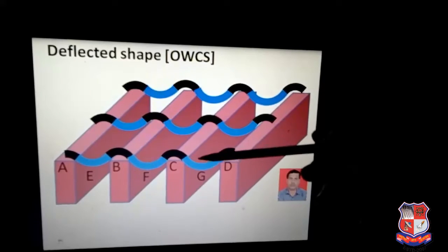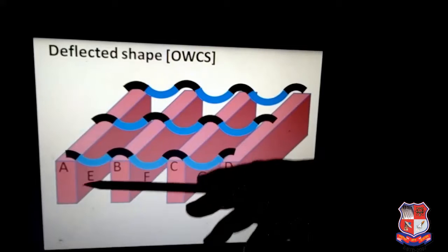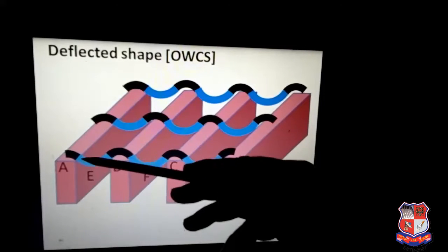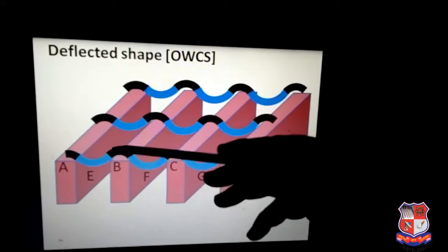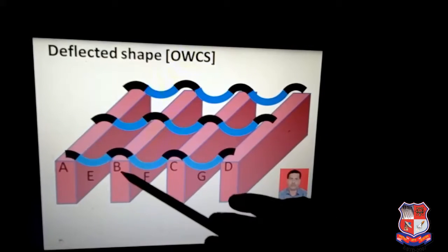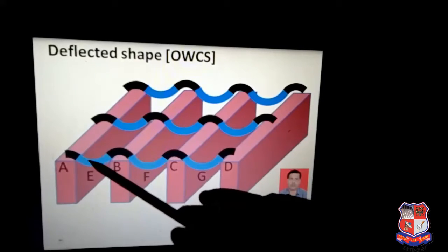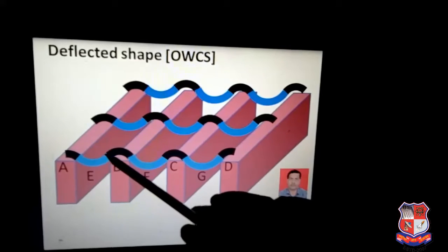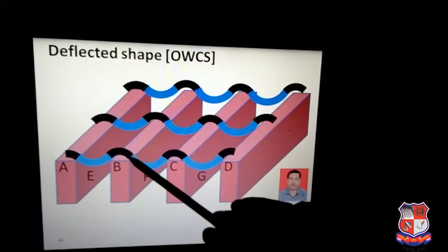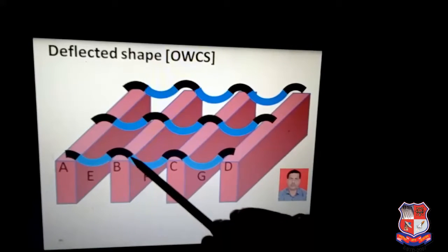Under the action of the load the slab is going to have some bending moment in each span. Under the influence of that bending moment, the slab is going to bend. This type of sagging bending in each span would occur, but the nature of bending on the support area is different. When the span bends like this in the span area, it is going to bend in opposite nature over the supports. So if this is a sagging bending, this is called hogging bending.